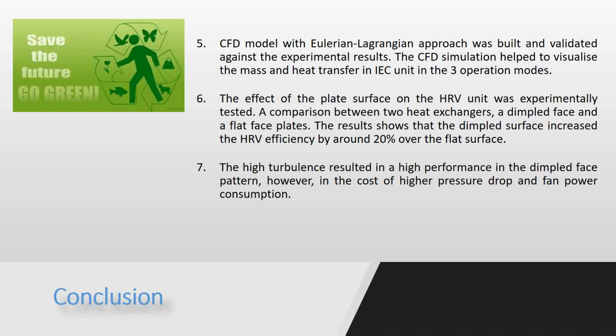The test showed that the dimpled surface increased the HRV efficiency by 20% over the flat surface in general, and by 50% in the case of increasing temperature, but in general it was 20% better. The high turbulence resulted in the high performance of the dimpled pattern. However, the higher pressure drop and fan consumption are the two disadvantages.